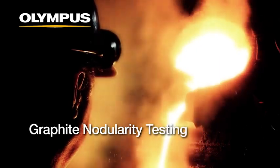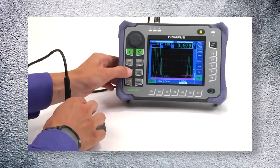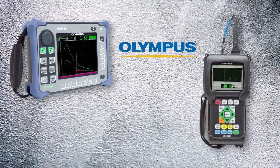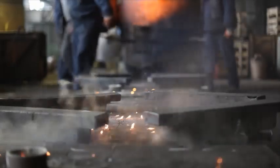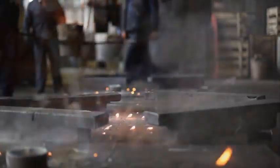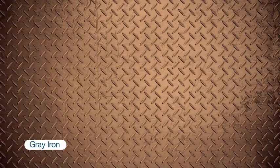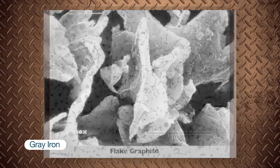Graphite nodularity testing in cast iron can be done with any instrument that is capable of measuring sound velocity. This includes an Olympus ultrasonic flaw detector, ultrasonic thickness gauge, or a pulsar receiver system. The practice of adding graphite to cast iron is commonly used to enhance the material's mechanical properties. Gray iron is formed when added graphite arranges itself in the form of thin flakes.